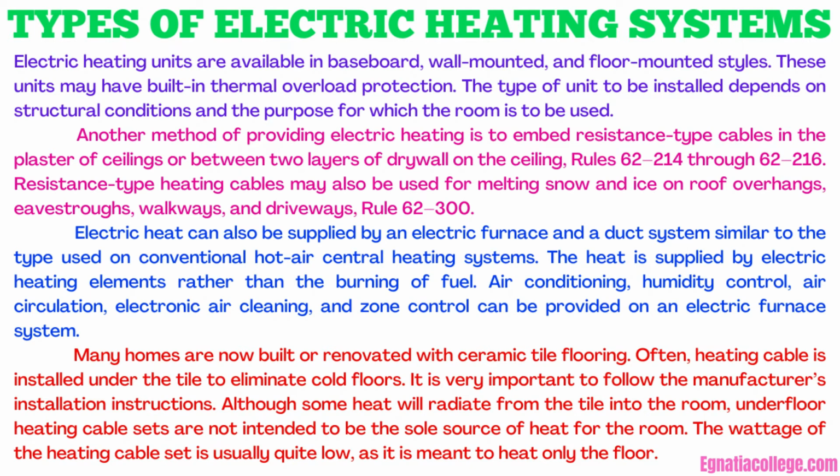Many homes are now built or renovated with ceramic tile flooring. Often, heating cable is installed under the tile to eliminate cold floors. It is very important to follow the manufacturer's installation instructions. Although some heat will radiate from the tile into the room, underfloor heating cable sets are not intended to be the sole source of heat for the room. The wattage of the heating cable set is usually quite low, as it is meant to heat only the floor.